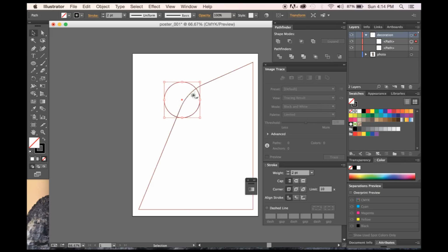And let's say I do want to have this cut out of this shape. I'm going to select them both, minus front, and there we have that. But say I still wanted that initial shape. I'm going to Command Z, select it, Command C to copy it, select them both, minus. Now say I want to put this back exactly where it was, I'm going to Command F.